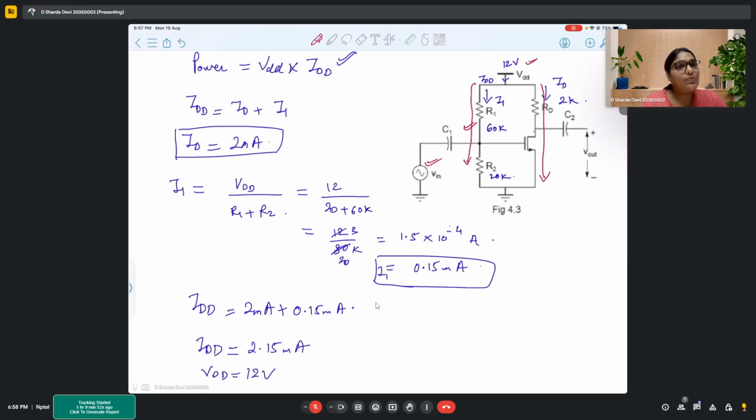No matter how many stages you have. But what is the advantage that you get in a multi-stage amplifier? That the gain increases. So that means your output is fixed, your gain increases. That means you can amplify even the smallest signals. So then the magnitude of input reduces, but output does not change because output cannot go beyond your VDD.